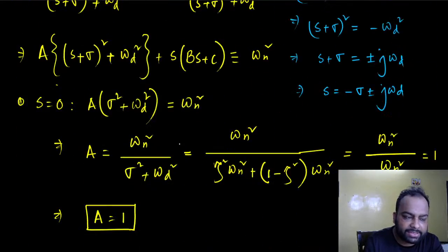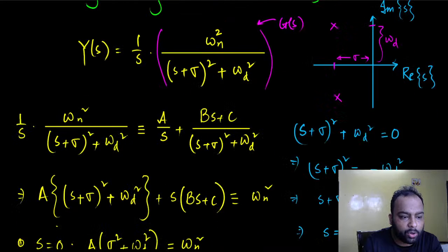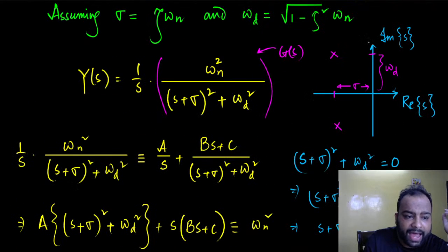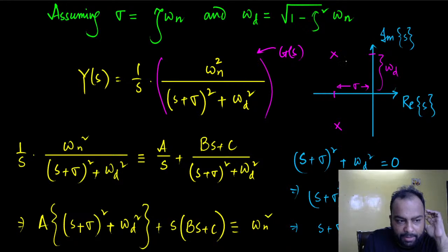We also calculated the step response, but before that, let's notice that on the S plane, which is again the complex plane, if we place the poles and zeros, you will see that they are complex conjugate pairs, and they are on the left half of the j omega axis, left half of the vertical axis here. This is called the left half plane, and we're going to discuss everything again. Just keep in mind, this is again a complex conjugate pole pair, but they are no longer on the j omega axis, but now they are on the left half plane, right?